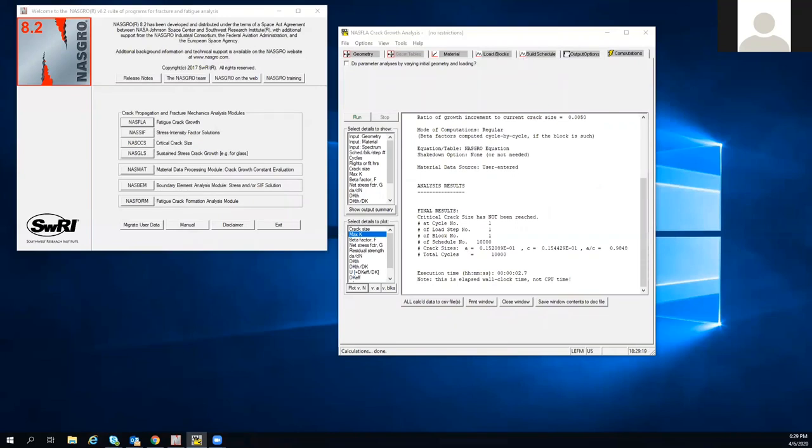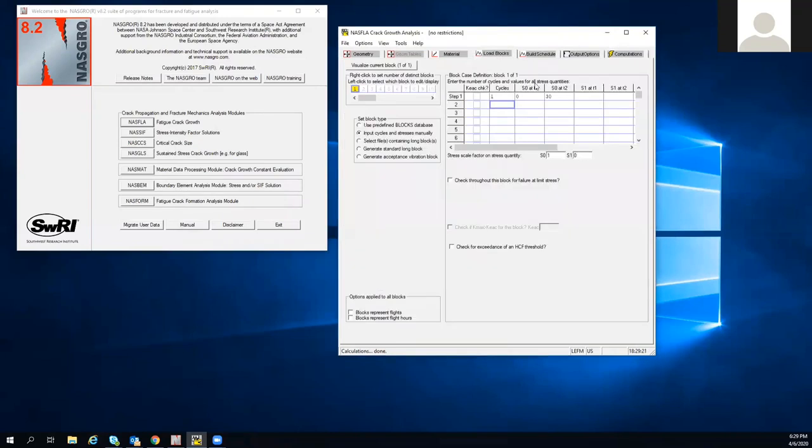So that was a simple case of just showing how to cycle a single stress amplitude. Typically, it's not so straightforward. Typically, we might say, okay, there's one case of going from 0 to 30, but there might be 100 cycles of going from 5 to 15, or there might be 1,000 cycles going from, let's say there was a compressive stress. Compressive stresses do different things at the crack tip. So maybe this was -10 to +10.